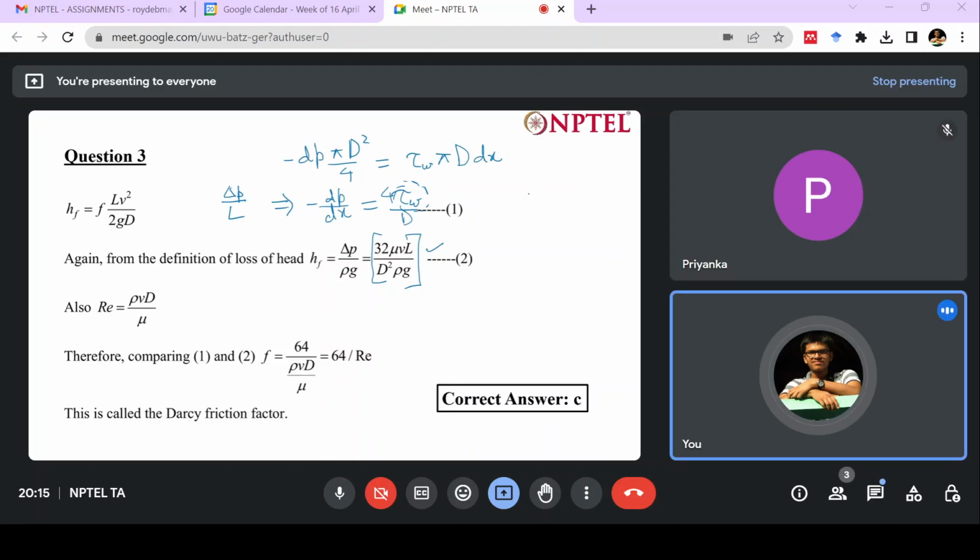So basically, if you solve for laminar pipe flow, if you simplify your Navier-Stokes equation, you will get something like this: del square ux over del r square, and this is constant. So this is a simple second order equation, and you will get some expression like what you got in your first problem.